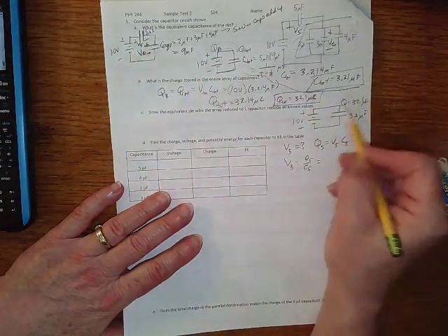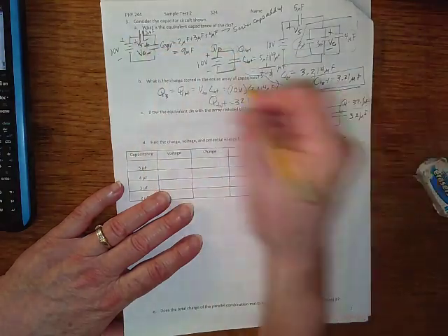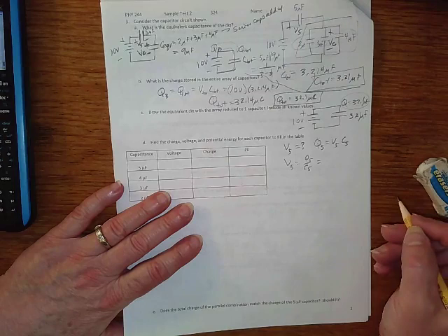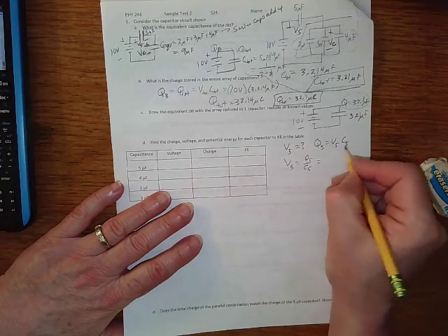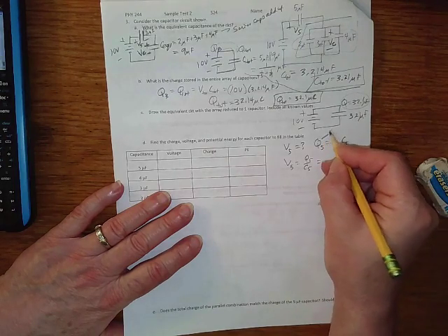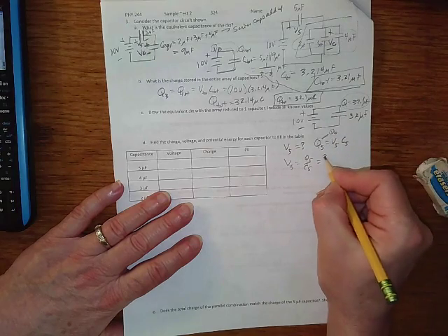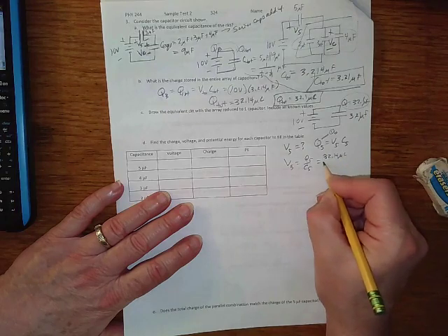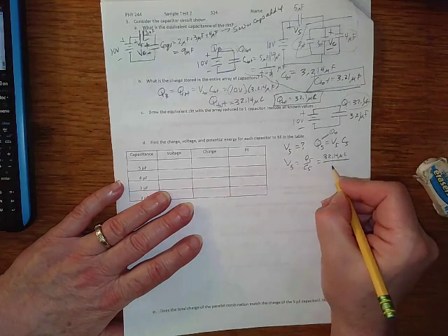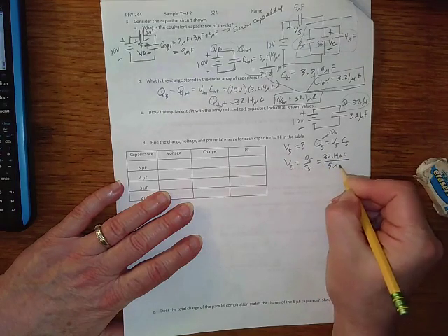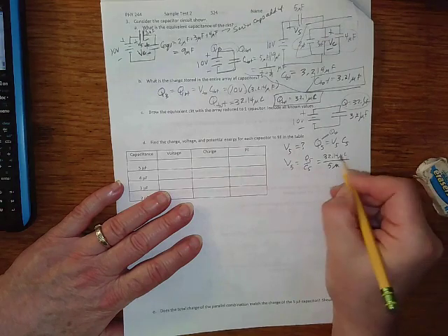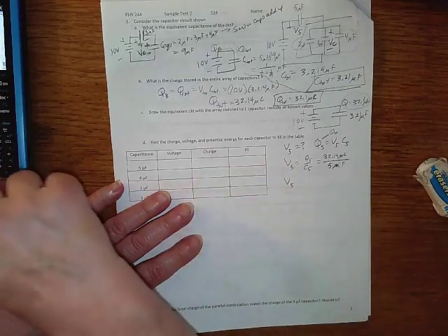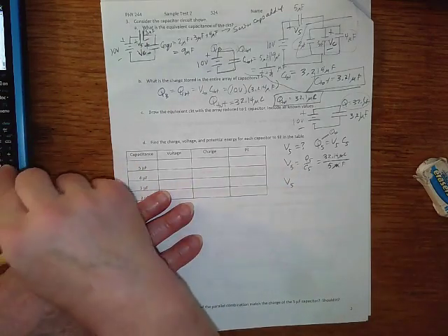The battery has this total Q, right? So the things in series, C equivalent 1 and the 5 microfarad both have to have that same equivalent Q. So Q5 is Q battery, right? And so we've got 32.14 microcoulombs over C5, which is 5 microfarads. The micros cancel basically. And so V5 is 32.14 divided by 5.